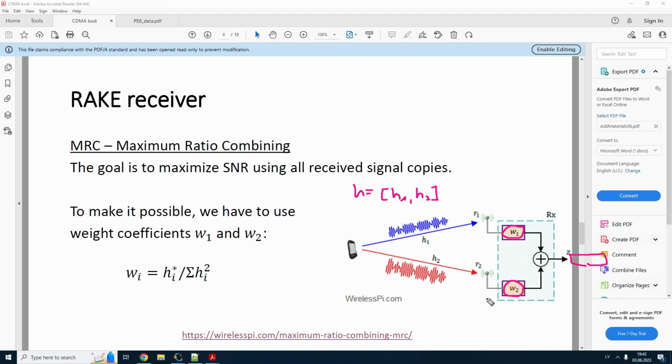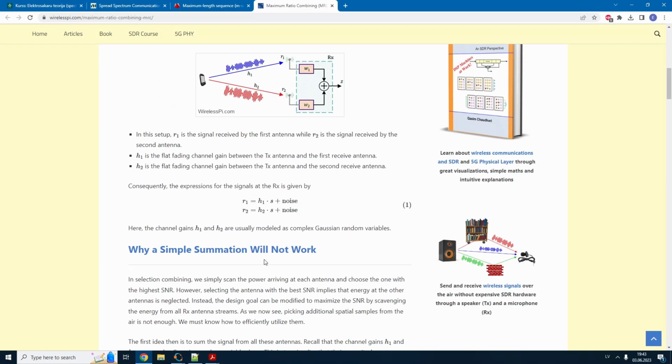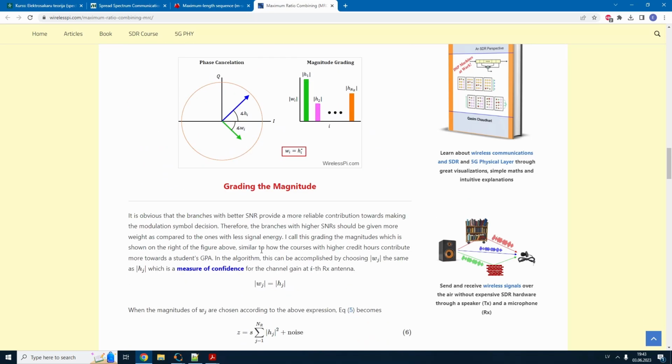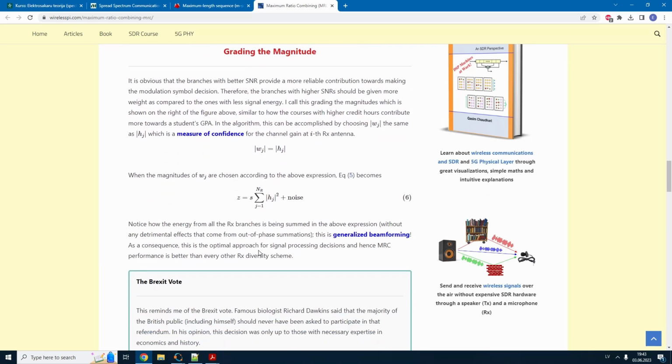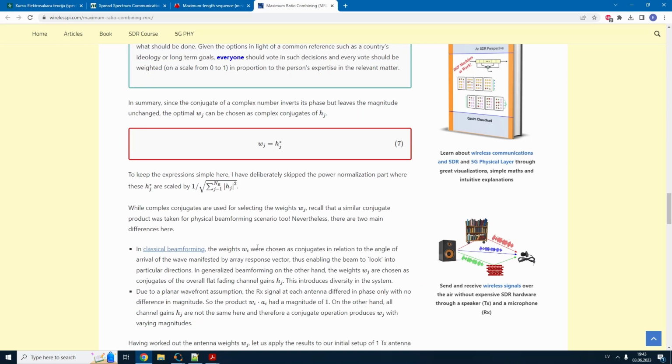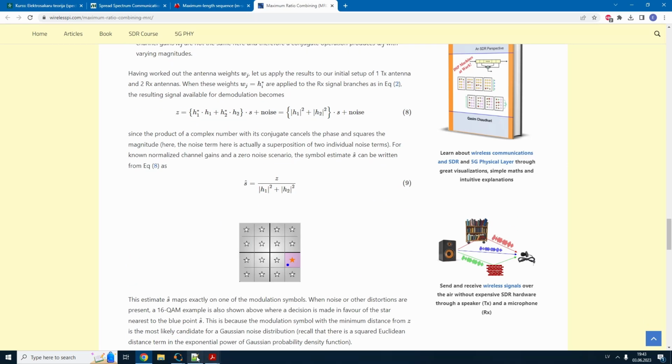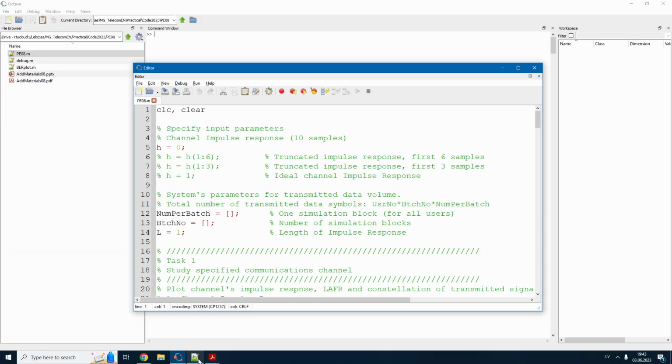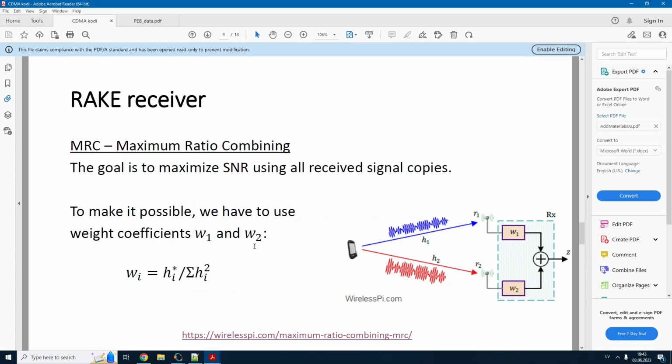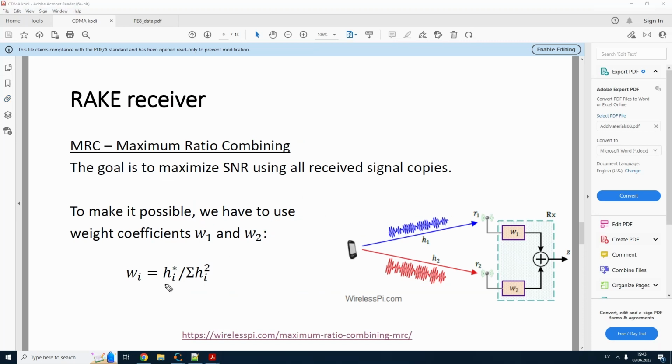recovered signal. So for more details, again, I would advise you to follow this link. It has some more mathematical background as well as the idea, and also how to calculate these weights. Basically, in a sense, they are almost the same as your impulse response, except for one thing. Your impulse response may actually be a complex one. This is particularly true for quadrature amplitude modulated signals. But since we are going to use them as a real function, the complex conjugate doesn't do anything.